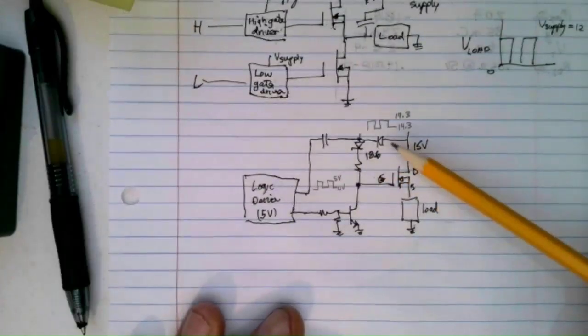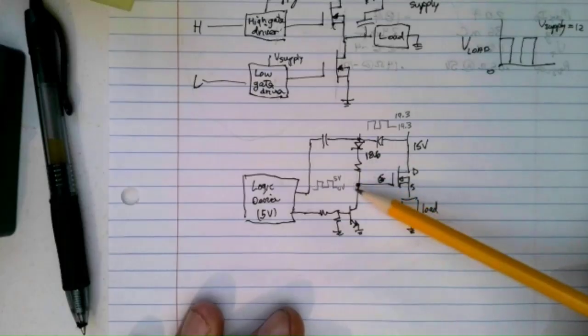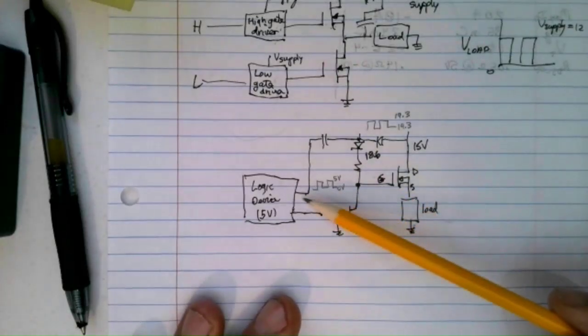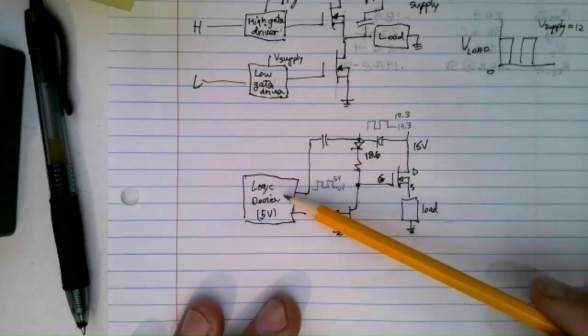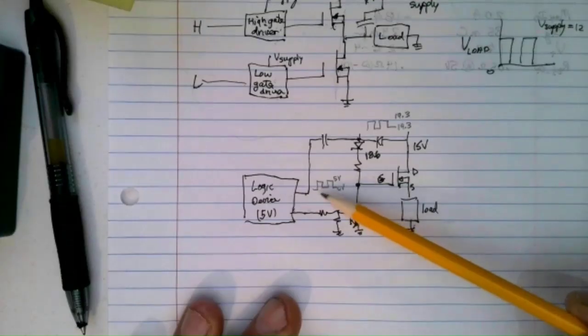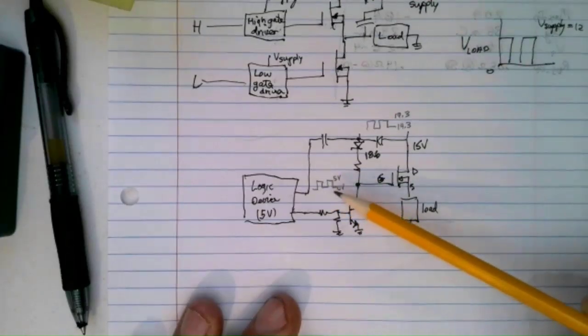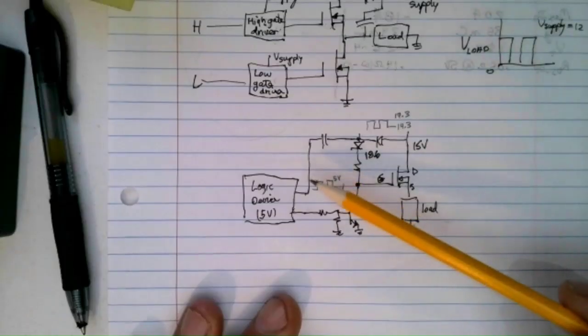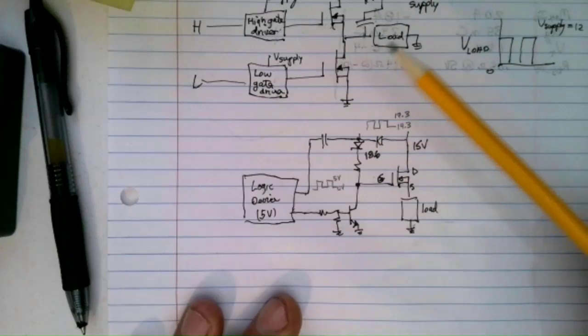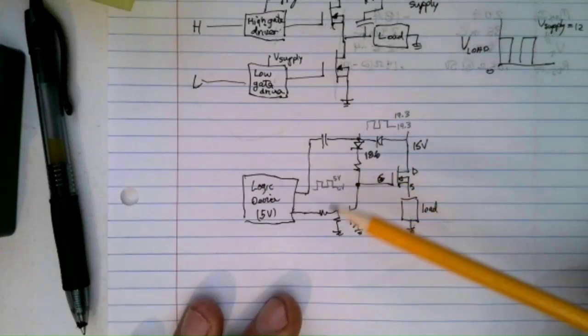Only in this case, with those two diodes, there would be supply minus 1.4, which would make it even worse. But if you were to have another output on this very same FPGA outputting, say, a 5-volt square wave, 0 volts, 5 volts, 0 volts, 5 volts, 0 volts, then we end up doing the same thing as what they did up here with the little bootstrap circuit.